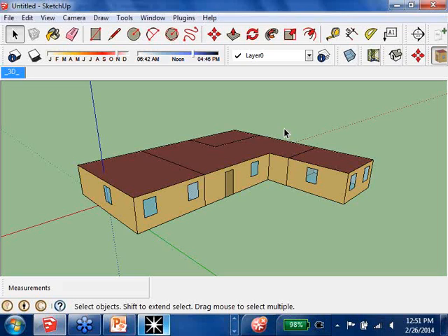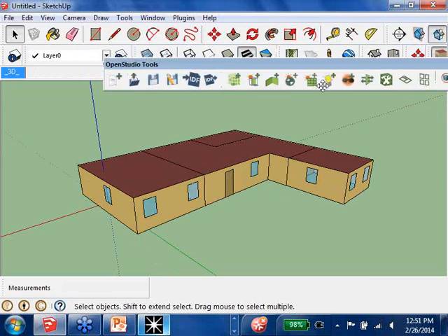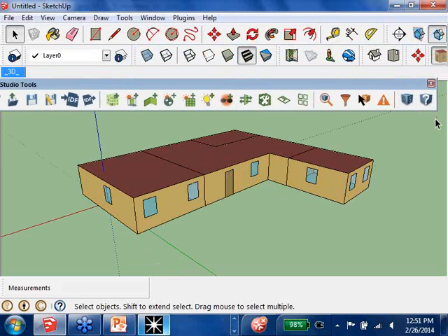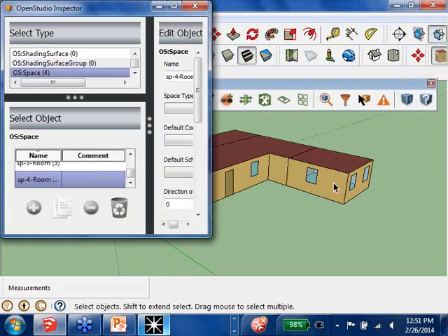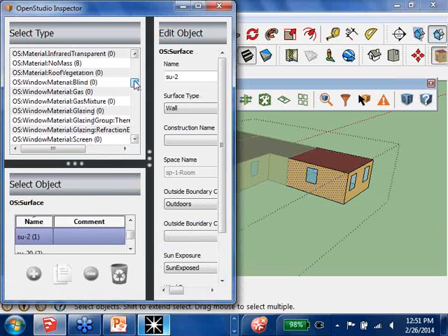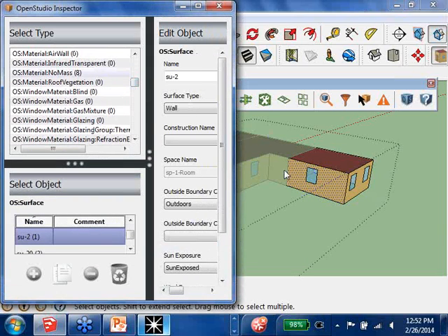OpenStudio? Mm-hmm. Do you know the answer to that? Yeah, so I don't know that. So remember with OpenStudio, there's an analysis pathway to where you can go from here, apply materials, and then run it in OpenStudio. So if you select, I guess, the inspector. Oh, yes, I do know that. If you go to any one of the materials that have come through, we'll actually see what has come through from the Revit properties.